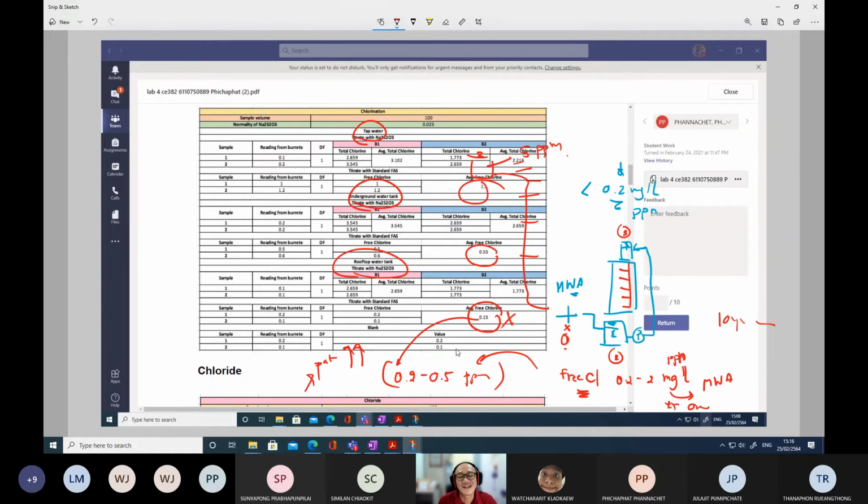So in this case, you should recommend to the persons who are in charge, who are taking care of the public water supply system in this building, to put in more chlorine. They should apply an extra amount of chlorine. Although the Metropolitan Waterworks Authority, MWA, adds up to 5 ppm, at the end, after long distance transportation, a certain amount of chlorine gets lost. So in front of the consumer's house, it may not be 5, it remains only 1.